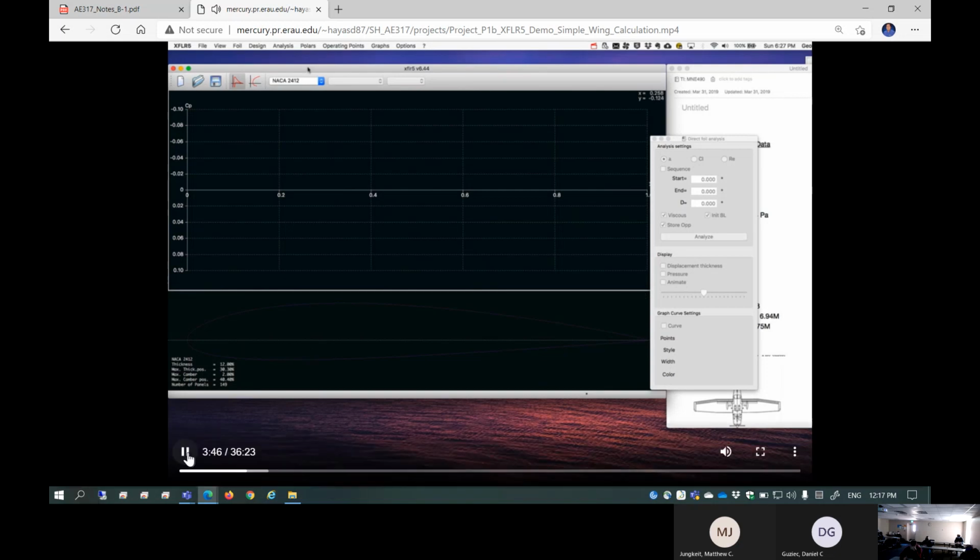Now I'm going to build the 3D wing. You can kind of see the shape. You see that? You cannot see it? I can see great. I cannot see here. I can barely see the shape. This is the NACA 2412. He basically picked up the data already built into XFLR5. If it's a NACA standard 4-digit, you can type the standard 4-digit into XFLR5 to read off the shape. Okay, go ahead.